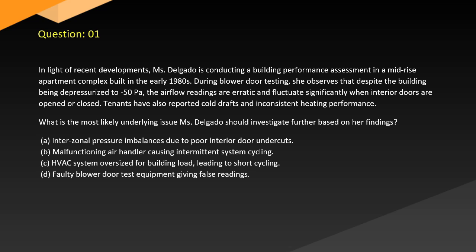Question 1. In light of recent developments, Delgado is conducting a building performance assessment in a mid-rise apartment complex built in the early 1980s. During blower door testing, she observes that despite the building being depressurized to -50 Pa, the airflow readings are erratic and fluctuate significantly when interior doors are opened or closed.